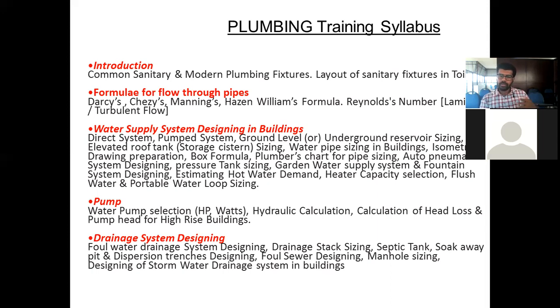From our concern, we need pressure. From his concern, he doesn't want to see that overhead tank at a raised level. So what do we have to do? We have to shift to another option. The other option is to give a pump setup or a booster pump. If we can't get sufficient pressure, we can give a booster pump after the overhead tank.